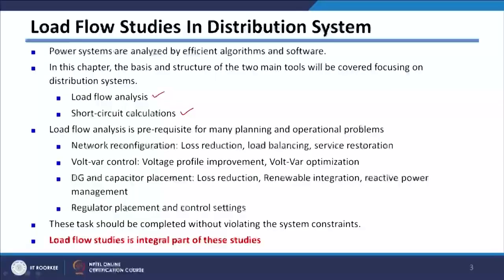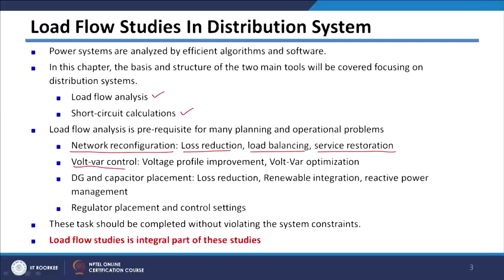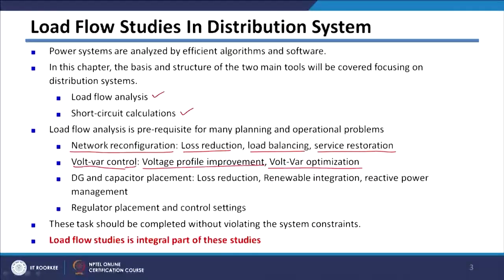Now, load flow study is a prerequisite for many planning as well as operational problems. Problems like network reconfiguration for loss reduction, load balancing or service restoration need load flow studies before doing it. Then for hour-to-hour control, which is basically required for voltage profile improvement in a distribution system, or hour-to-hour optimization, you also need load flow study results so that we can arrive at proper hour-to-hour control in a distribution system.